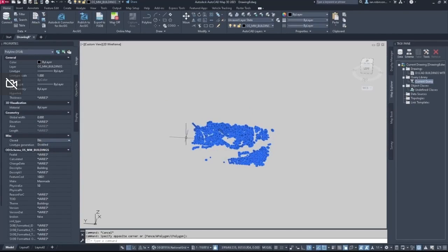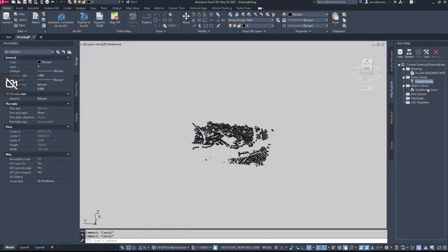Say no to that. Oh, that comes up because all of these are still part of the query here, and it means that if I change something here, I can go and change the original drawing. It allows you to bring a single drawing into multiple other drawings and all edit that one drawing. It's quite clever, really. But if I just detach it, that will stop that message coming up.